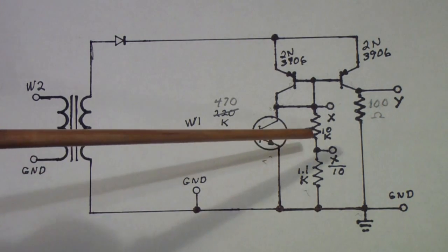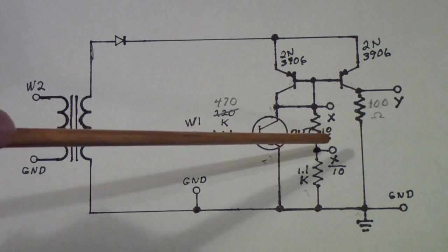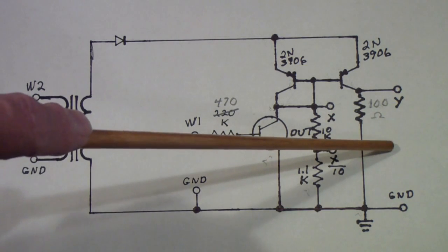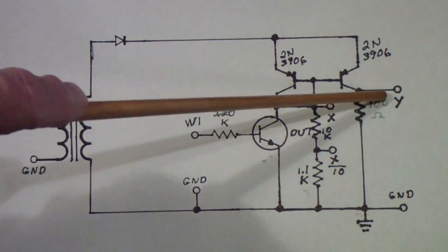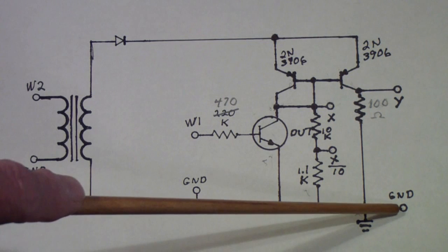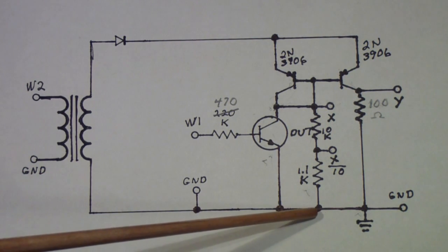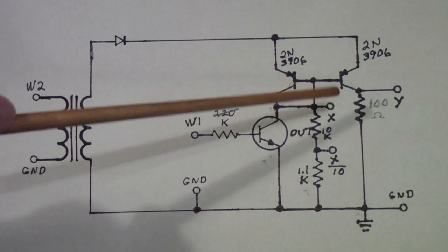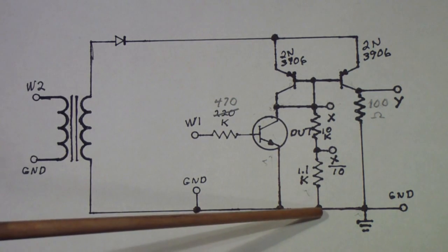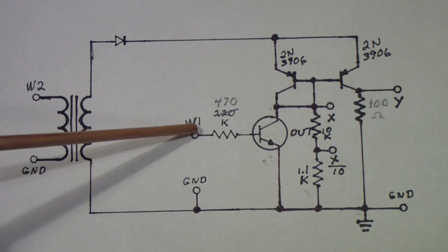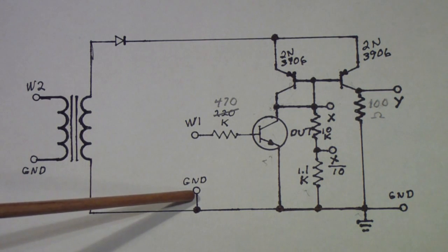So you now could use this circuit with the Analog Discovery BNC board, or with any other oscilloscope, even those that you cannot float the ground on, because you may notice now everything is referenced to ground. The X, or the X divided by 10, is referenced to ground. This waveform generator is referenced to ground.